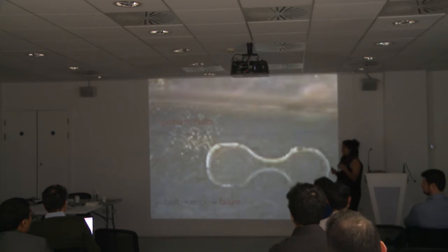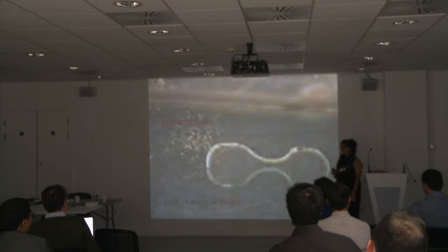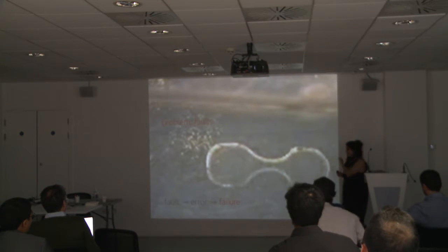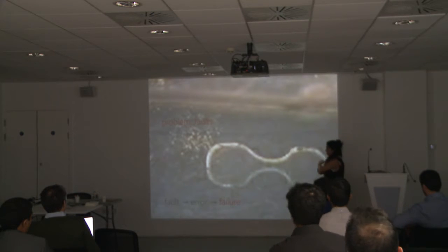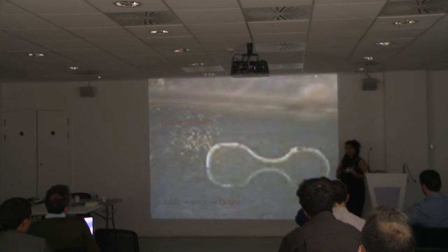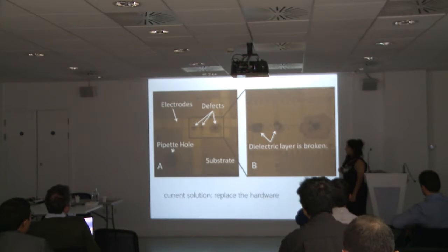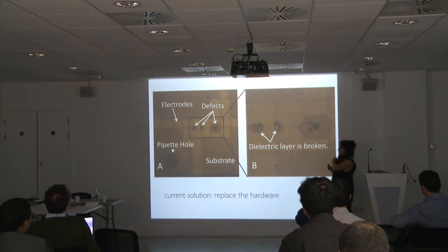In terms of digital microfluidics or droplet microfluidics, there are two things that could go wrong. One is during the movement of the droplet. Here you can see an unbalanced split, not very high resolution. What happens is if you split the droplet in an unbalanced way, you have the wrong concentration, and that's a transient fault. And here you can see the hardware faults.